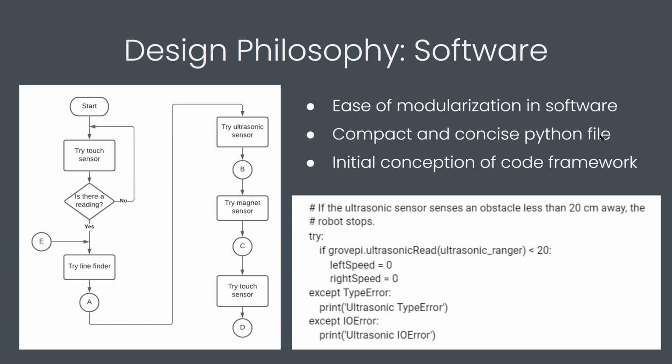Following that, at block C was the IMU. This used a counter variable to determine the path the macro would take. Its options were to turn right, for example, at a branch to the cargo drop-off zone, go straight to ignore the branching line, unload at the drop-off zone, and reload at the landing zone. These functions would interrupt the main code, run the assigned functions, and then return to the main code to continue